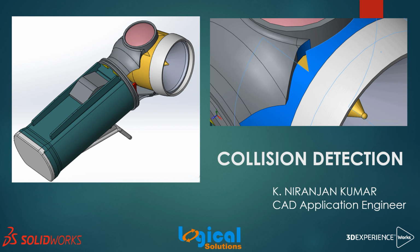Initially, collision detection and interference check are the same. In both cases, two components of an assembly try to occupy the same space, or they enter into each other's space. But the difference is that interference check is done between static components, meaning both components should be stationary, whereas in collision detection the same interference is checked during dynamic motion. Components are not stationary. In this way, collision detection is also termed dynamic collision detection.